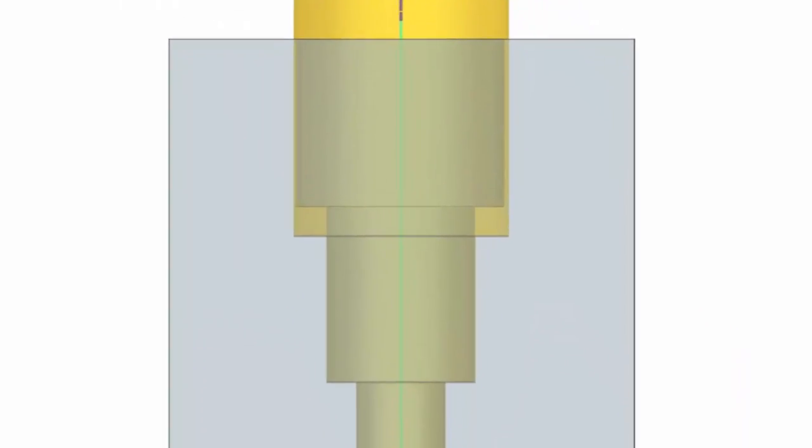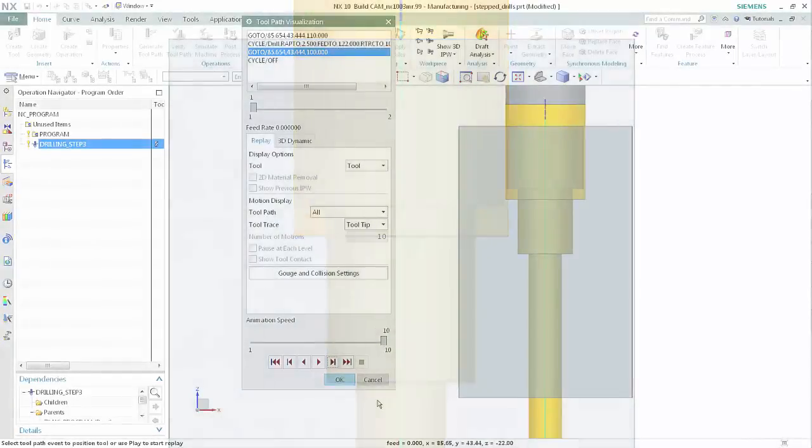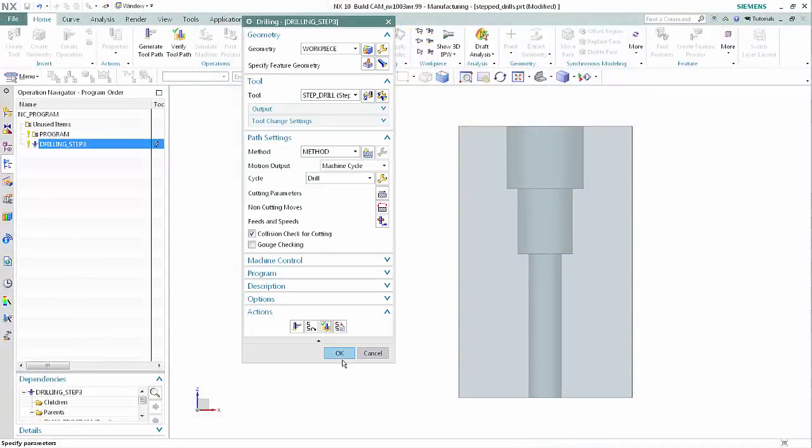The tool drive point cuts to the bottom of the specified machining area. The upper tool shoulder is allowed to exceed the diameter and cut the depth of the Faces Cylinder 1 machining feature. Again, this is an explicit action to drive a particular tracking point to a particular depth and is therefore seen as an intentional gouge. Click Cancel. Click OK to complete the operation.